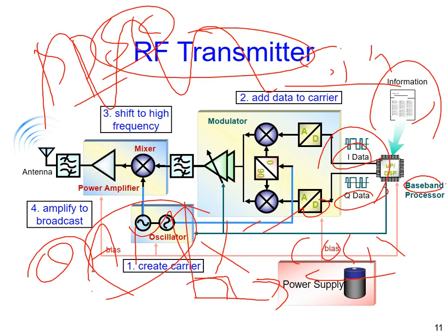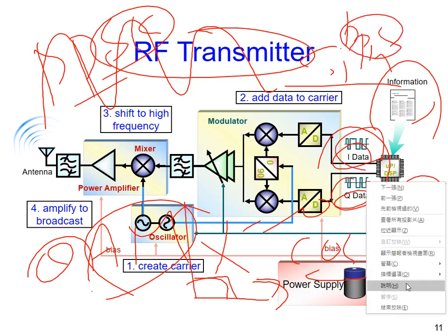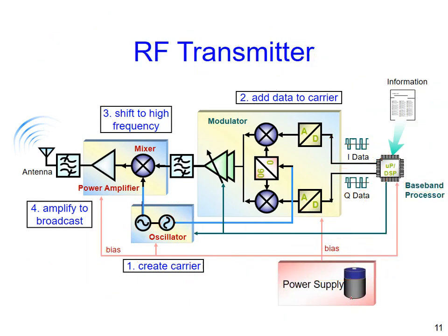You can transmit 2 bits at the same time. Okay, that is the brilliant idea for humankind. We can double the transmission speed. Oh, not the bit rate, bits per second, through such kind of I data and Q data. I means in phase, 同向. Q, quarter, right? So it means what? 90 degrees in difference, orthogonal, 正交, with the original one.